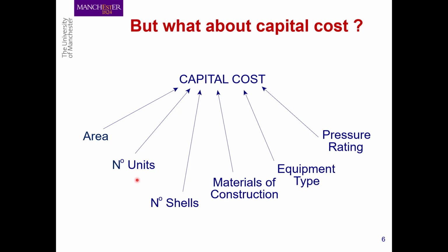Thus, targeting the minimum number of shells is also useful and realistic in comparison with number of units targets, as it provides a better opportunity to compare different HEN designs.